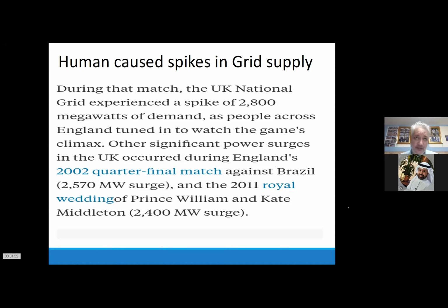You can see it downstairs with the current. So for example, the one makes the current with 6.5, the other one with 7, the other one with 8. So if you have even multi-string inverters with different amounts of currents, but the same or similar voltage, then you have to check. That's the fine tuning I always say: put the 8 amps together, put the 6.5 together, put the 7 amps together, and then you will see you've got a much better output.